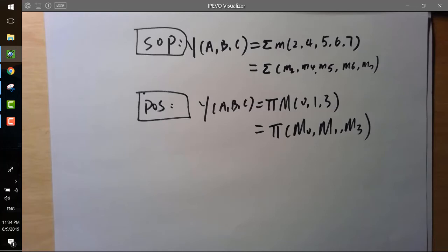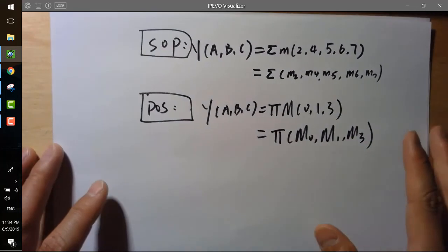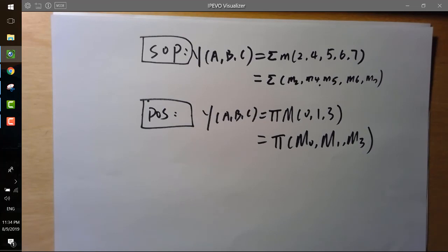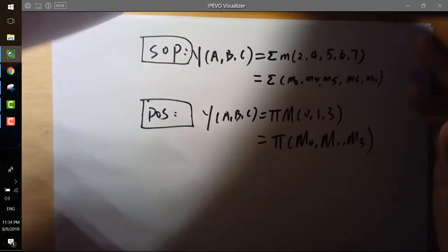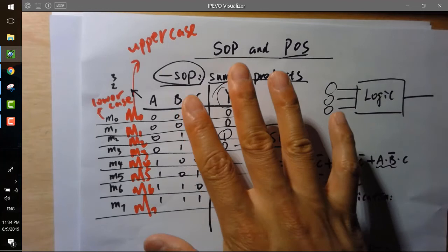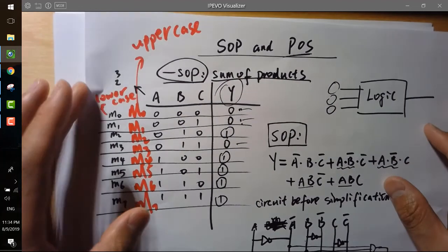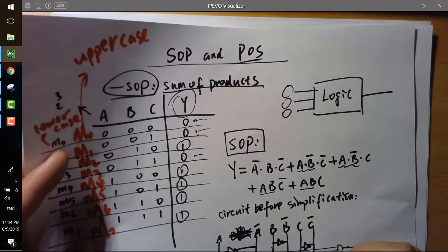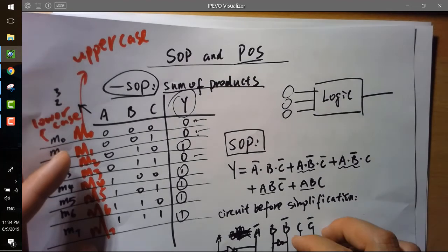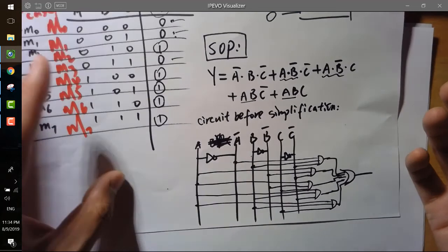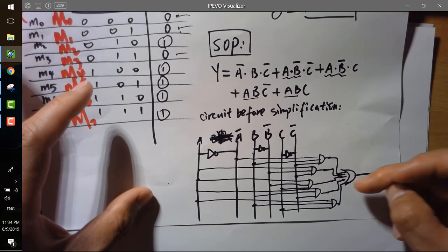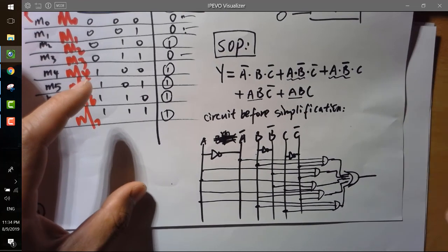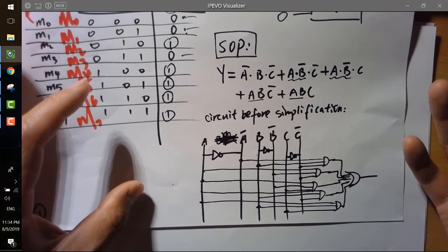Okay, so that's the beginning of the introduction of how we design a digital system from a given logic. They are static combinational logic, and how you do it is you get a logic expression, then you simplify it, and then you draw the gate circuit. The gates consist of just CMOS transistors. Actually, you are able to build them in LTspice.